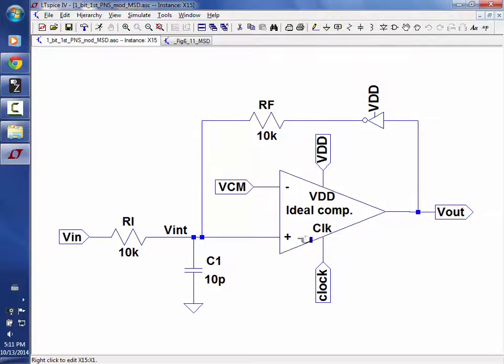Since I'm going through here and I'm going to the minus terminal, I'm inverting the signal, so my output would have a 180-degree phase shift. But if I was really worried about hardware, I could get rid of the inverter. Generally, they don't in hardware because they want this to be really isolated and tied to very precise reference voltages.